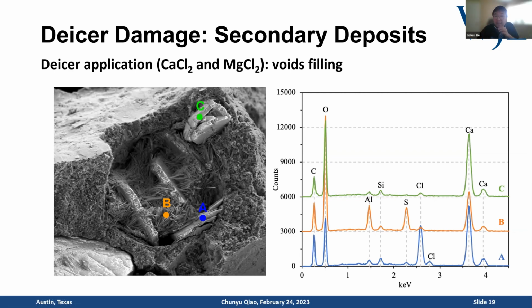Okay, yeah, actually, I may have one further question about the water reducer and pores. I'm not quite sure what you mean that there's not really a significant influence of water reducer on the pores. Is that all types of pores or some specific types? Because based on my previous experience, especially in self-consolidating concrete, the usage of water reducers may increase both the entrapped air voids and entrained air voids a little bit. Yes, Diallo.